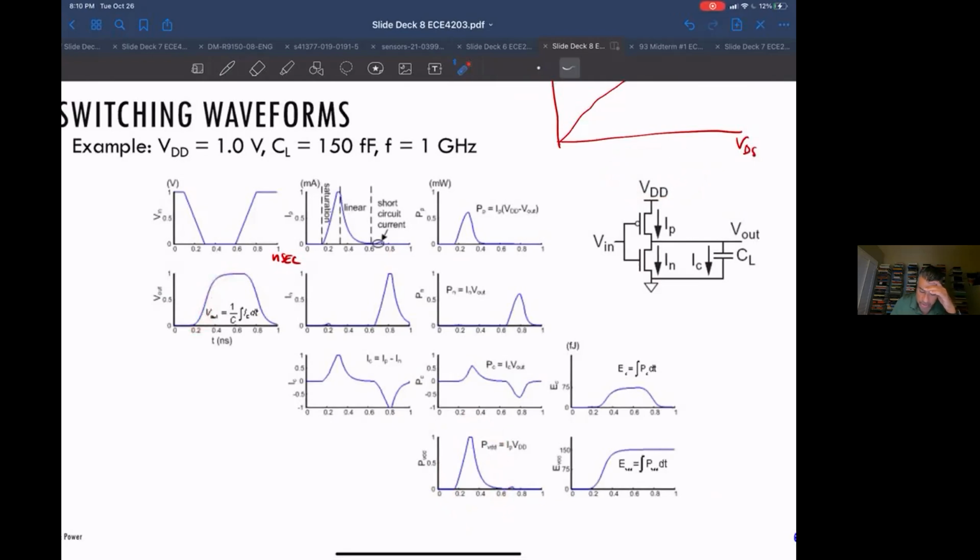Okay, and there's no power consumption. I mean, there's the crossover current here when both N and PMOS are on, but there's no power consumption from the VDD when we're discharging the capacitor, because the VDD is just disconnected from the supply. So then furthermore, when we calculate the energies, when you look at the energy on the capacitor,